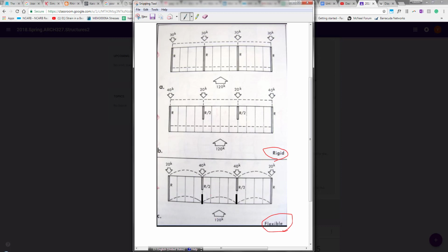So basically, let's say this table is a diaphragm, right? And these two legs or four legs are trying to anchor it to the floor. And you can do that. Unfortunately, it moves. But if these two are anchored, then you can see how if I rock this table back and forth, that back and forth force gets transmitted to this wall and eventually goes down to the ground. In this case, the tabletop is the diaphragm.